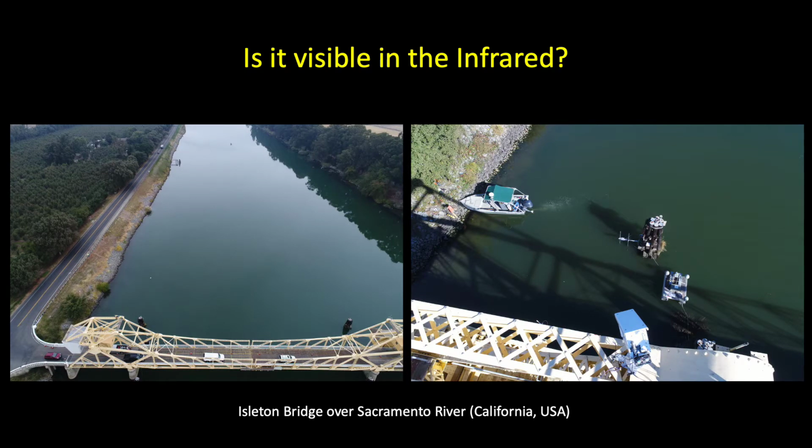So how do we capture infrared images in the environment? What I'm showing is an image of the Sacramento River, and here on the right I have a thermal camera, a FLIR infrared camera, about 1 megapixel, that is aimed obliquely at this region of the flow. Here we have acoustic instruments mounted on a horizontal bar that are hanging into the water. You'll see actually they form a Kármán vortex street, which we'll see in a minute. Piling cluster, a larger diameter that will also shed a Kármán vortex street. And we have ground control points used to georeference the images located in a variety of points, which will become even more clear in the infrared.